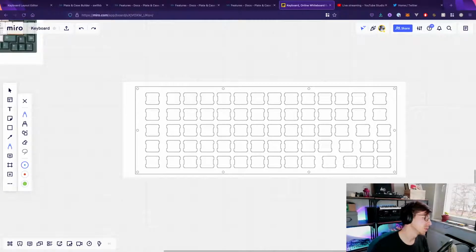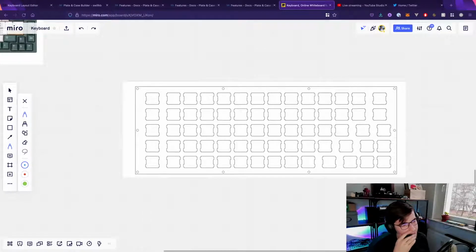Usually the microcontroller that you would put in a PCB won't have that many input pins. So usually what you do is you make a rows and columns concept, and that's what I'm going to do right now. With a staggered one, you have to draw the exact lines, and because we have a semi-staggered here, we need to decide which keys belong to which row and so on.